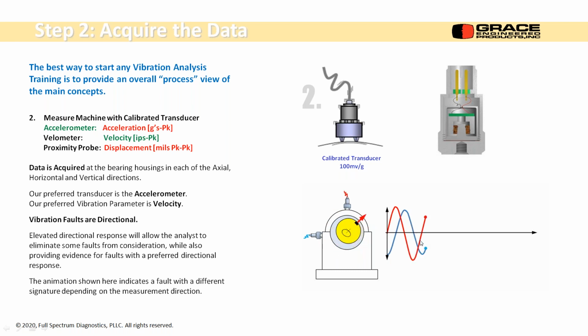So what does this mean? They're out of phase by a quarter of a revolution. The heavy spot takes a quarter of a revolution longer to go by the blue peak. And these two directions will have different amplitudes. They can have different frequency content. They can have all kinds of differences. So if I don't measure the horizontal, the vertical, and the axial, I'm going to miss something. Thankfully, a lot of transducers now are triaxial, and that MEMS accelerometer is also triaxial. So we'll pick up all three directions simultaneously.